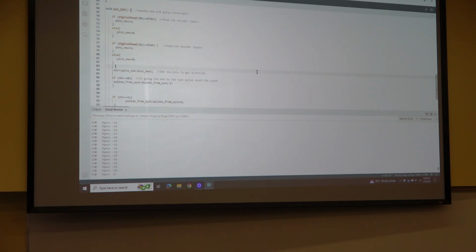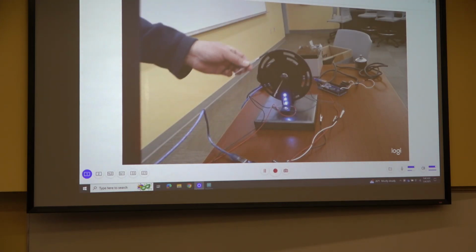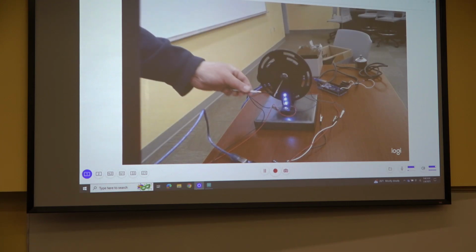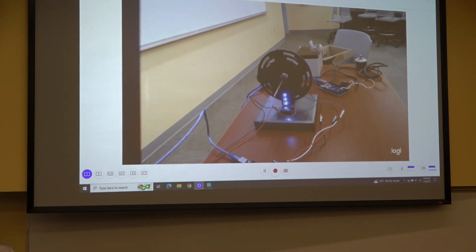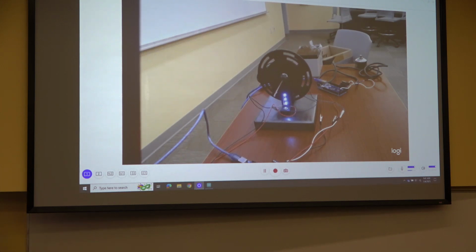So the software I've got going into my little demonstrator, I've got my channel A pulses coming around here. I've got 5 slots, another 5 slots, equal angle, but offset by 25%. I've got my light sources for my phototransistors down at the bottom. Every time one of these little windows pops up, the phototransistor becomes conductive. It allows the input to go low and triggers an interrupt on the Arduino.